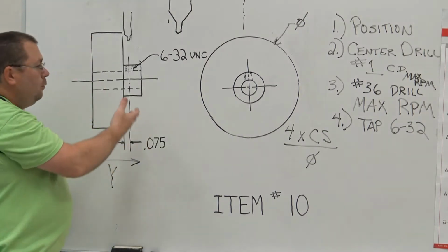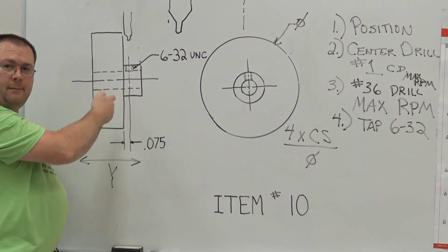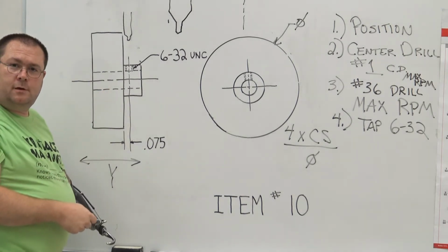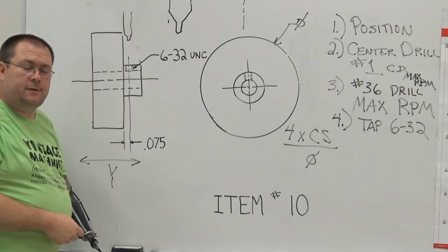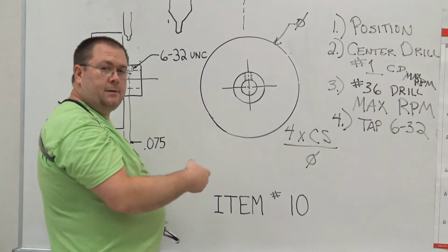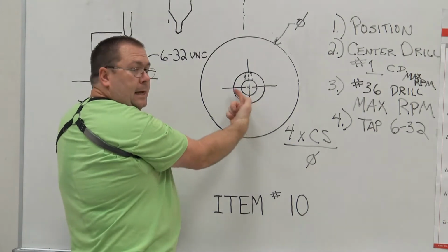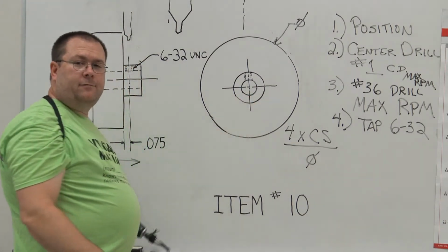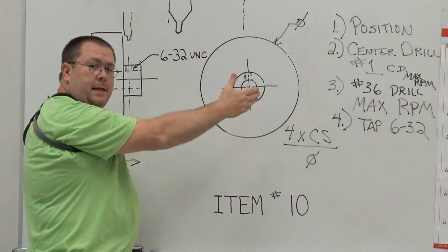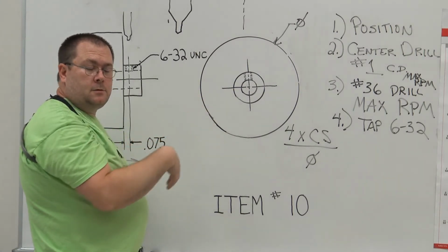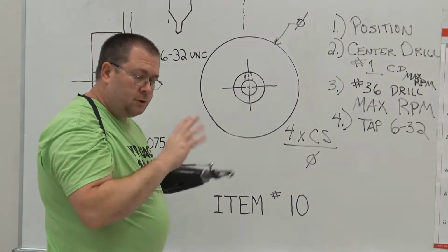That becomes a problem for us. So now we've got a part that's got a hole in it bigger than the set screw that we use to fasten it to the crankshaft. So we're going to have to take the part out, rotate it, reposition it to another side, right? And we're going to have to redo all these steps back to the edge finding. So if we do this right the first time, don't start the spindle.